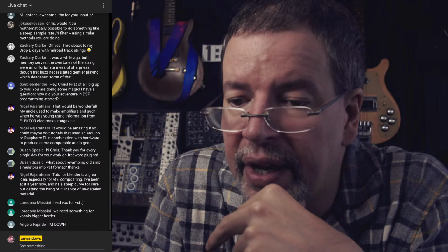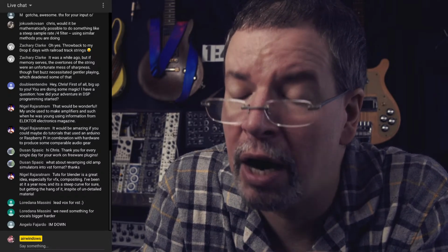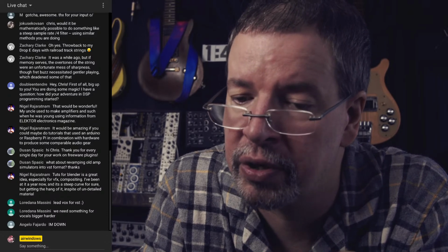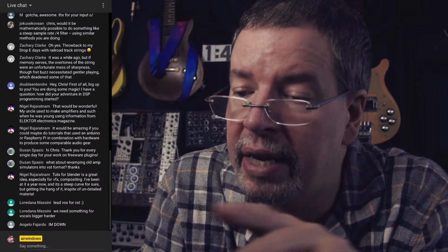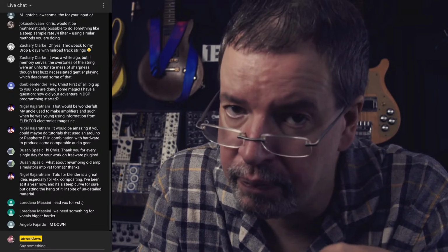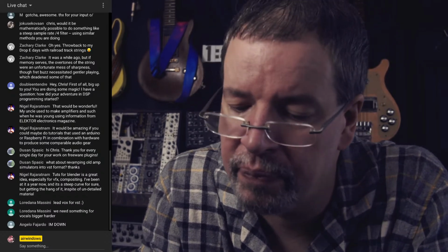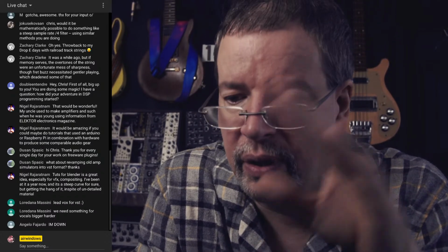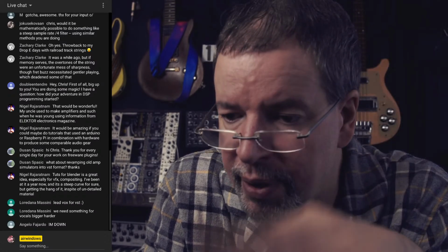And that's an XOR gate, so you patch some of the positions on the outputs of the shift register together so that it's feeding back the end of the shift register into the beginning again. And if you do that, you get the Turing machine or something like it. You get a loop of logic values, and it's clocked with the clock, and it keeps stepping through.